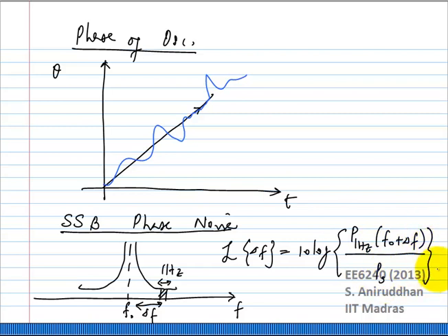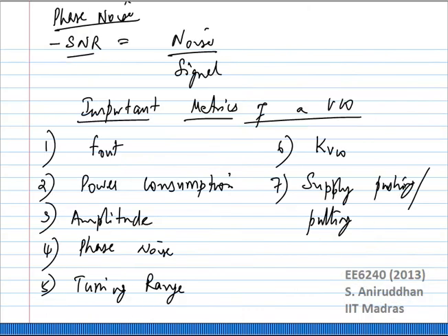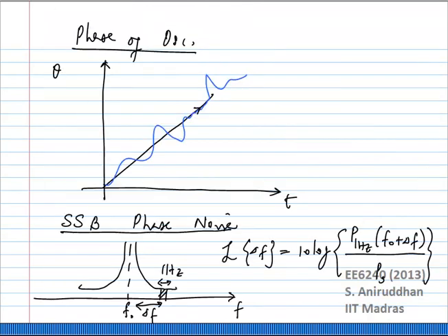the signal power. So remember yesterday I said it is represented as some negative SNR dB, or noise to signal ratio, is what we should have said. So what I meant is this noise to signal ratio. And so you take it as 10 log of the noise power over the signal power.